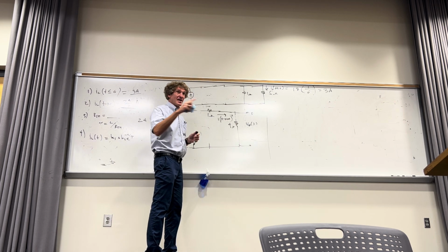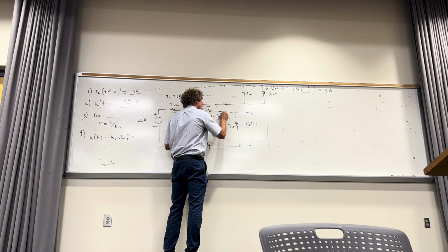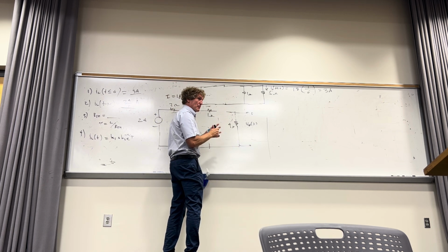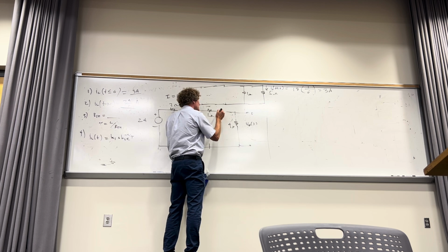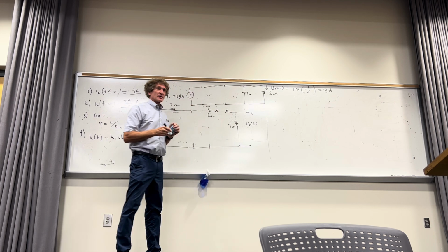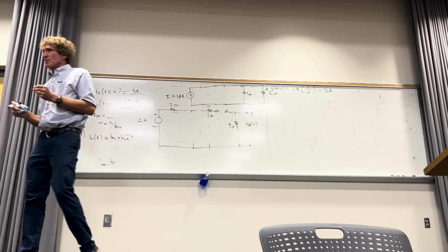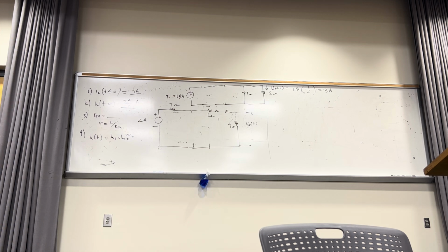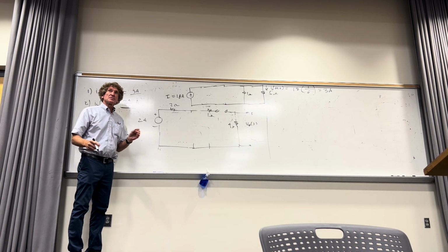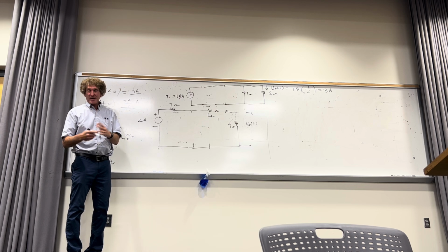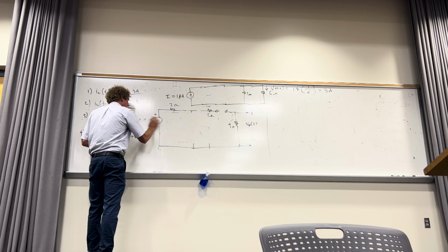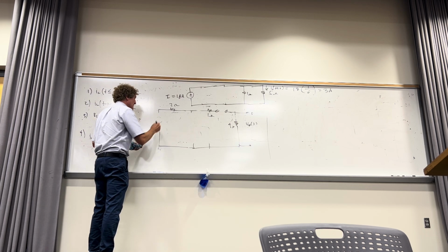Now this is important. I just happen to put a wire here, but if I open that, I'm trying to show you the image. Just rip it out, right? Those two terminals indicate where you want the Thevenin equivalent resistance. Does everybody follow me? But there's a source left, right? It's a voltage source. What do we do with a voltage source? Short circuit. Wire short circuit, they're all correct. So I make it this.